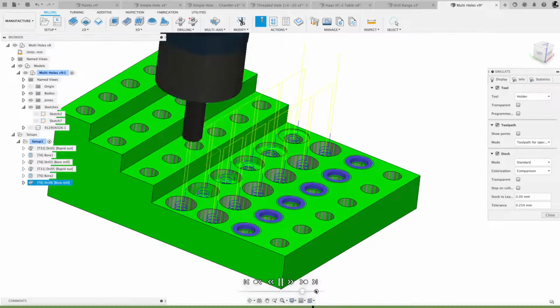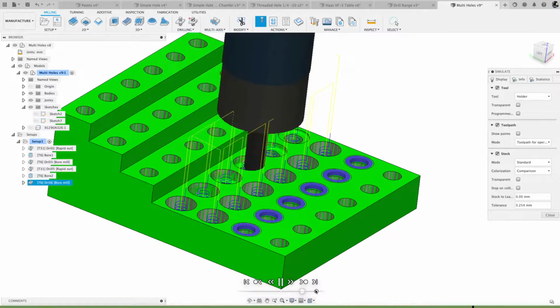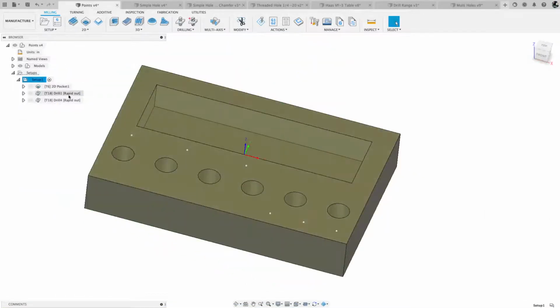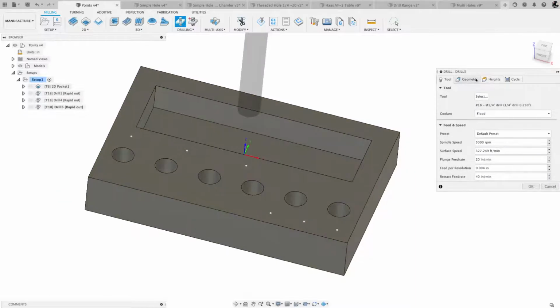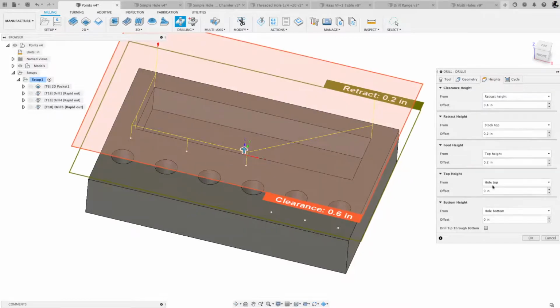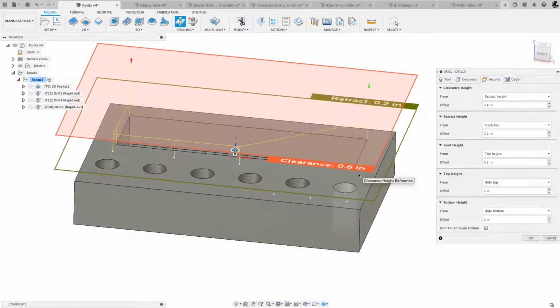Looks like we have a question from SoCal, Plymouth, and Dodge. So we need a solid model to drill holes. No, you don't need a solid model. Remember that first example I showed you is this guy under points. When I selected a drill, I can just do points. I can just start clicking and it'll give you the holes. The problem with that though is it doesn't have the associativity to a cylinder, and then you lose a parametric ability there. So then it becomes very prehistoric. You need to tell it the height and the depth and things of that nature.